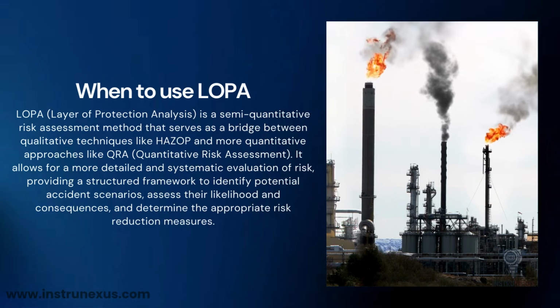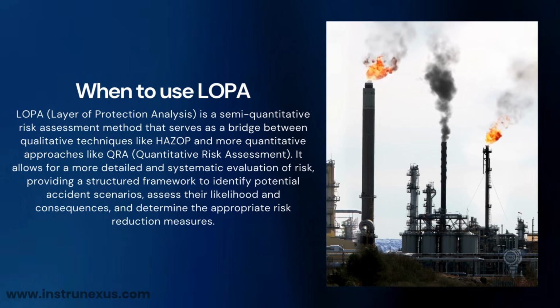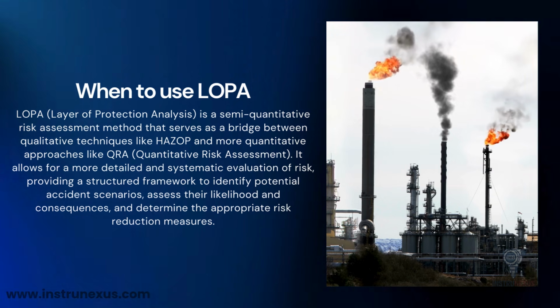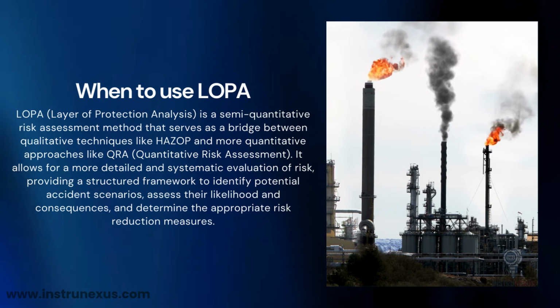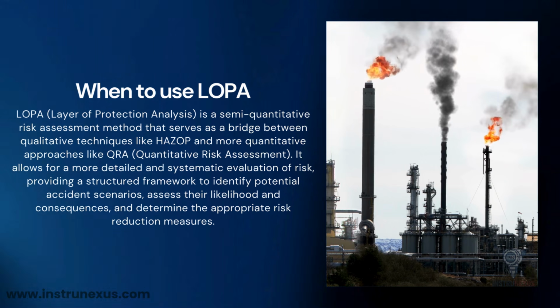When should you deploy LOPA? It is best used as a bridge. A HAZOP is great for identifying hazards, but it's subjective. A quantitative risk assessment, QRA, is detailed but expensive and time-consuming. LOPA sits in the middle. It provides a consistent, simplified, yet numerical framework.